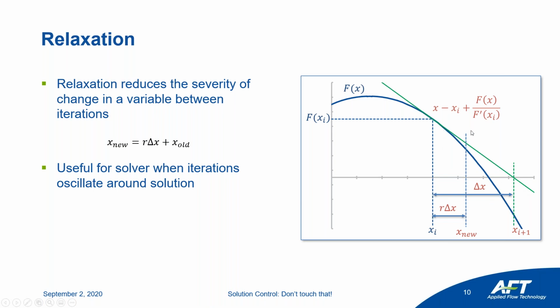And so as it iterates, it's not going to exit this loop. And so that's where relaxation can help. So this was the auto span for iterations. This is checking that if this happens more than 100 times, then you should probably start relaxing the solution, which instead of creating this very large jump, now it'll start to inch closer and closer to the root.